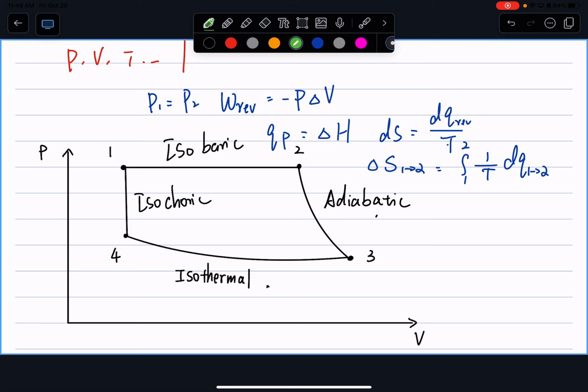All right. For the adiabatic, well, we know plenty of adiabatic processes. Well, the most important one is Q equals 0. And because of that Q equals 0, we went over a derivation of T3 over T2 equals V2 over V3 to the power R divided by C_V,m. Now, C_V,m is the molar isochoric heat capacity. And if you don't remember where that comes from, in the lecture notes we went over that. It's the adiabatic expansion of ideal gases.